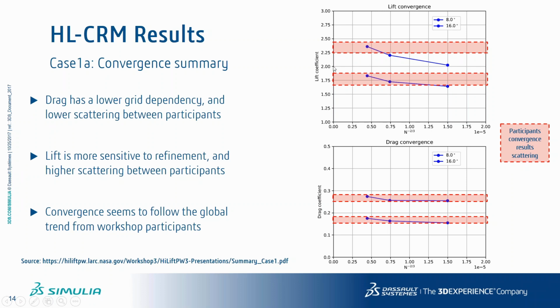So you see that it's a graph that plots the lift and the drag as a function of N to the power minus 2/3. It's a way of checking convergence. When you go to the left, that's when you refine your resolution, and when you tend to 0, you tend to an infinitely fine solution, when the distance between two lattice nodes tends to 0. So you've got an almost linear trend, and you see that you should converge to something.